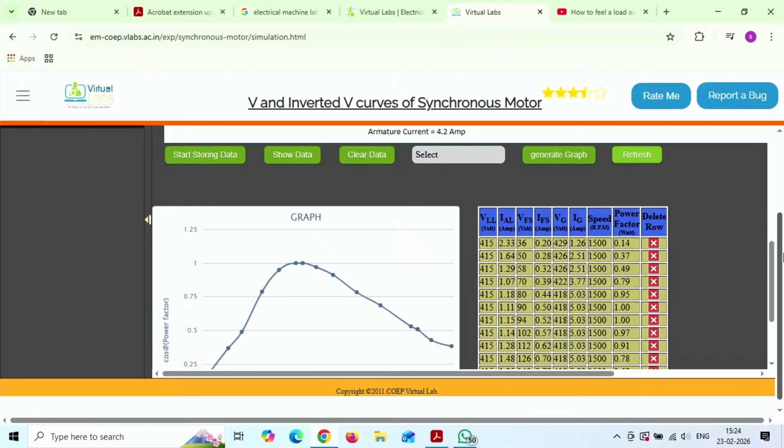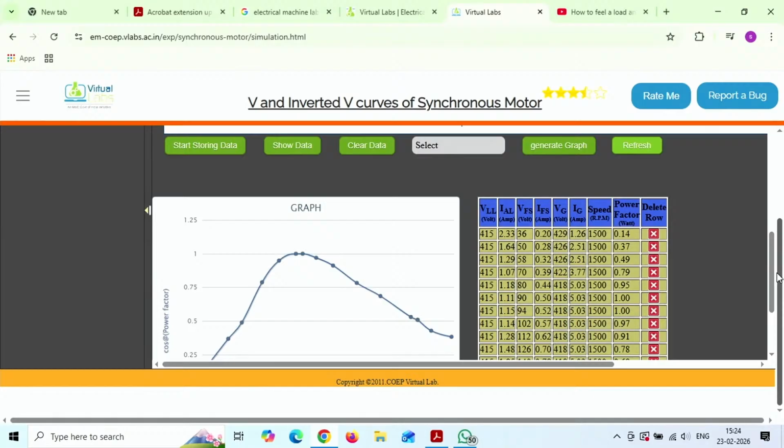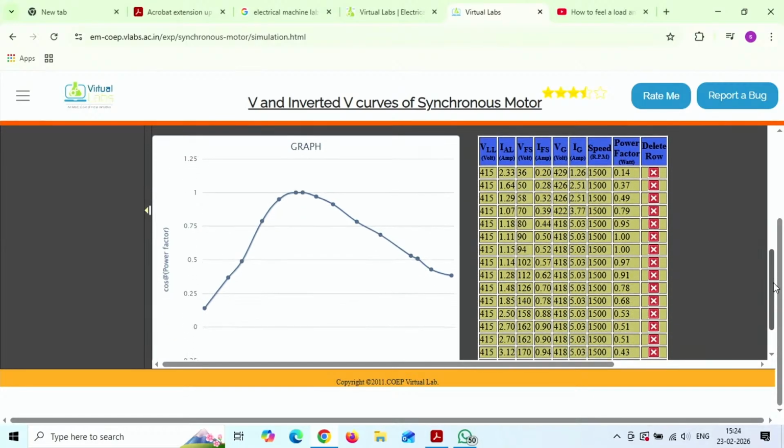First, stator resistance, stator leakage reactance, magnetizing reactance, and the core loss component, the energy loss component per phase. Then on the rotor side, we have rotor resistance R2 and X2. In case of wound rotor, we have rotor leakage reactance.